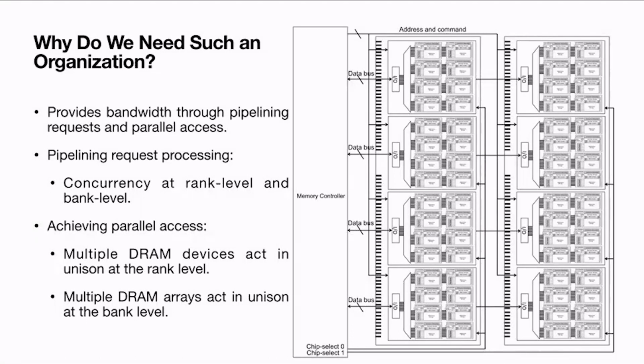Because you have the inherent drawback of the DRAM arrays working at a lower frequency, but because you have this parallelization and pipelining, that reduces or overlaps most of the computation time, and that reduces the average memory time, so that you can supply the data to the processor in maybe 200 to 250 cycles, because of all these optimizations. Otherwise it would have been even more.